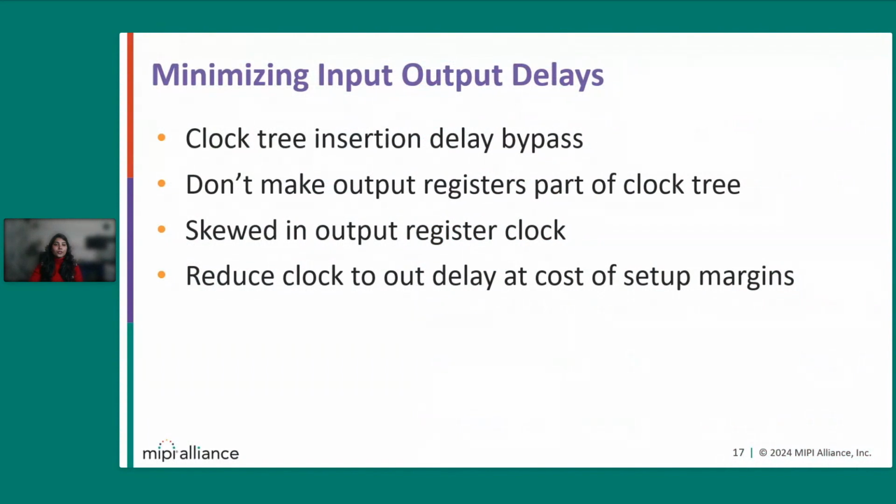So we know that the MIPI I3C standard defines a time called bus turnaround time, but here we will touch upon the output delays, input to output delays, and we will see how we can minimize our input to output delays in the design. One way is to bypass the clock tree insertion latency by isolating the final output registers from the design clock tree. And how we will do that, we will see in the next slide.